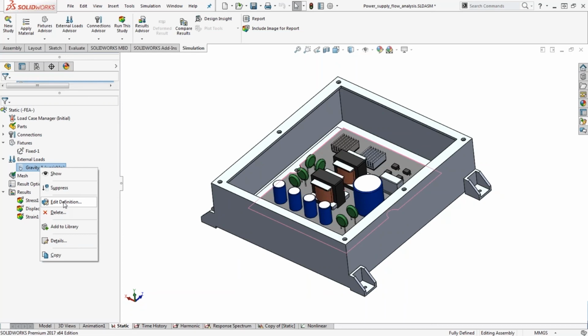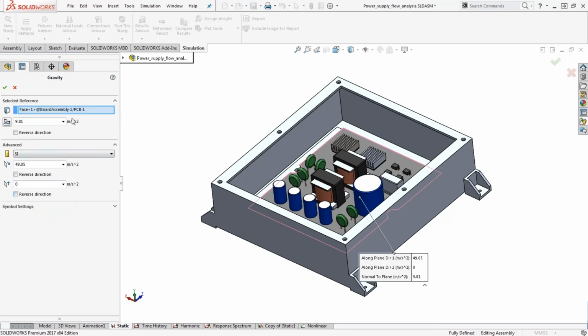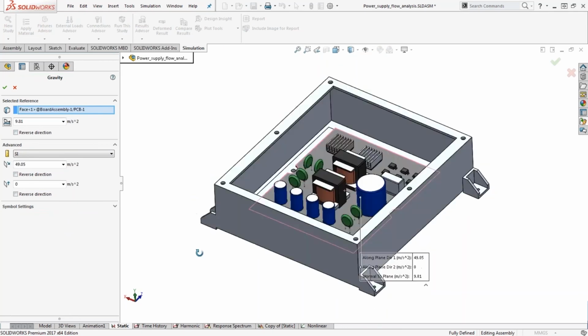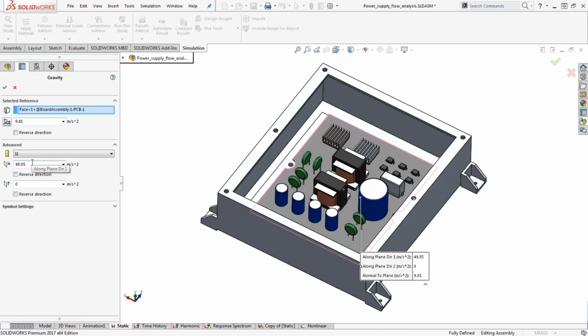You see that this assembly consists of all these parts. When I go into the material, again, we're assuming a linear elastic material here. We're utilizing the database within SOLIDWORKS, and it's incorporating all these properties to give us those results, which are stress, displacement, and strain. So we apply those material definitions for all the parts, and the green check lets us know that we've defined one.